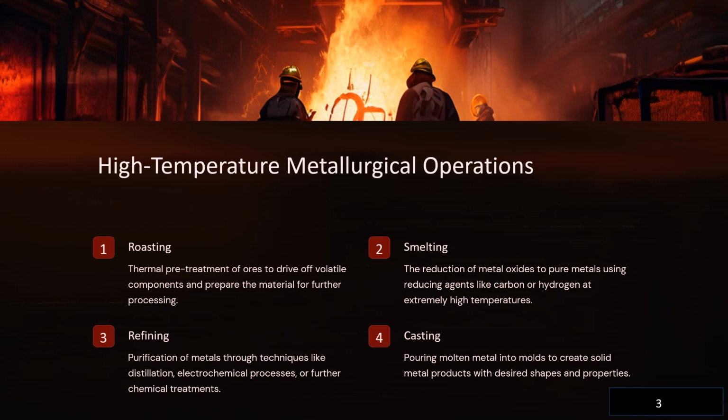The ores subjected to roasting are mostly purified by froth flotation. Roasting is a complex technique of thermal gas-solid reactions, which include oxidation, reduction, chlorination, sulfation, and pyrohydrolysis.